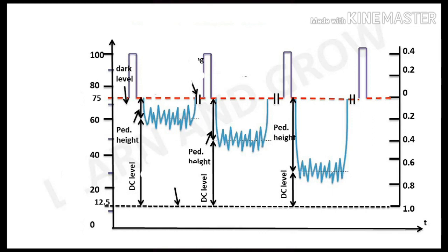A relatively long blanking time blanks not only the vertical retrace lines, but also a small portion of vertical tracking at the bottom and top. Pulses in vertical blanking time: the alignment pulses inserted in the composite video signal during a wide vertical blanking pulse are shown in figure 7.7. These include equalizing pulses, vertical alignment pulses, and some horizontal alignment pulses.